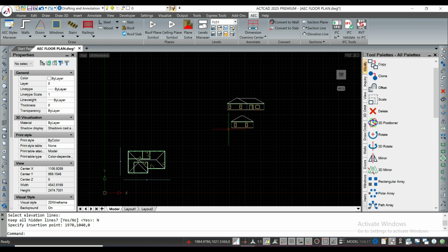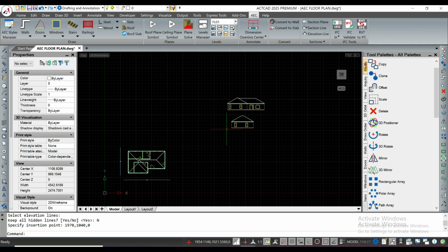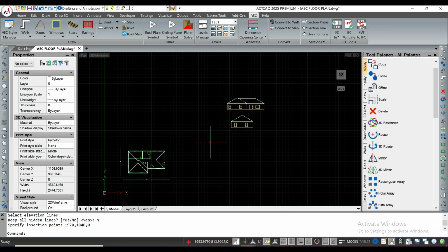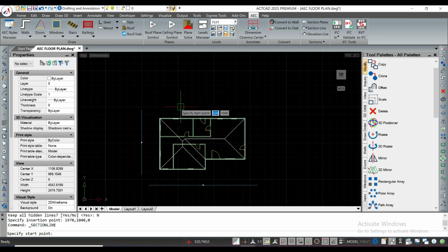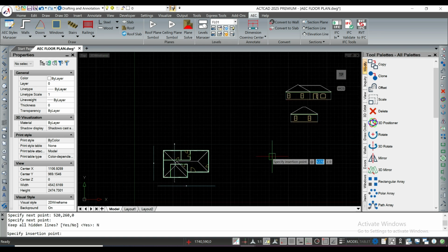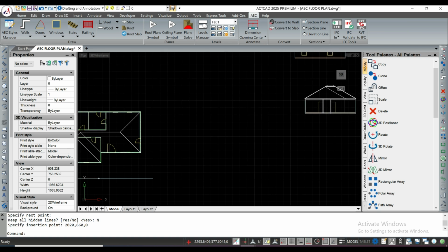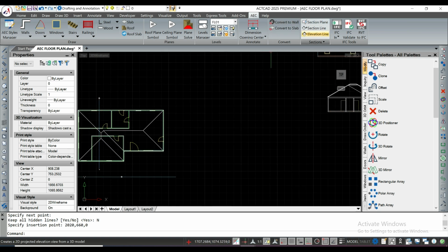It's time to create a couple of section views. Now, in general, they work the same way. I'll click on the section view tool, and again, I'm prompted to draw the line. Remembering my lesson from the last elevation, I want to make sure the direction I want is the section to view. Notice this time, instead of ending at the second point, I can choose to continue. We'll do that next, but for this one, I'm done. I'll follow the same workflow to place my new section view.